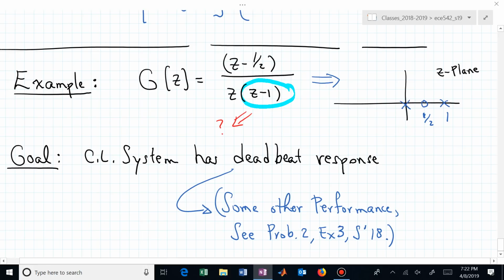Now, instead of having all of your poles in T sub C of Z at the origin, you might have your dominant poles determined by performance specifications. So you now have a Z delta as a complex conjugate set of poles.